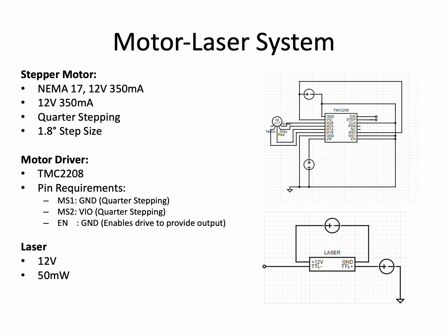The stepper motor is controlled by 2 inputs sent from the Raspberry Pi. These 2 inputs are the direction that the shaft needs to turn, as well as the time that the shaft needs to take a step. The micro-stepping operation deemed most suitable for this project is quarter-stepping.